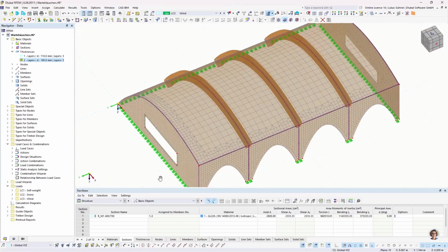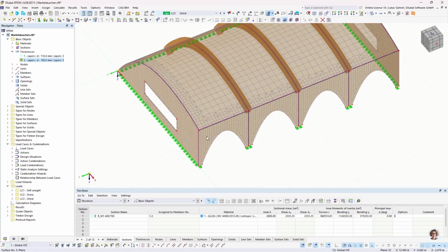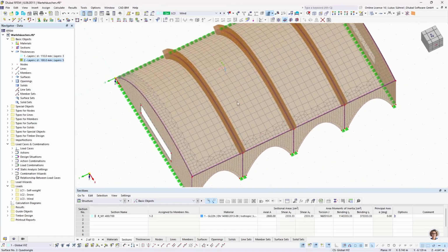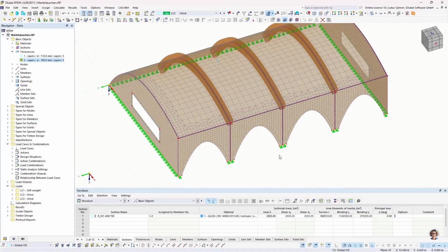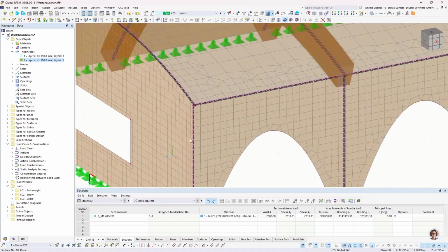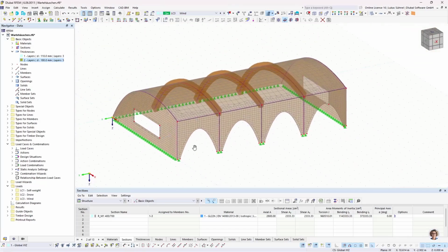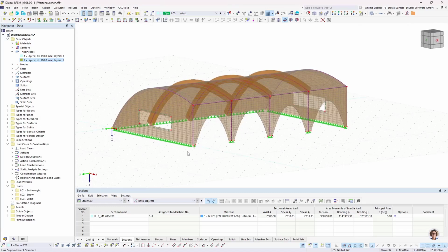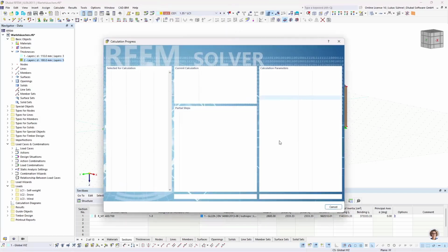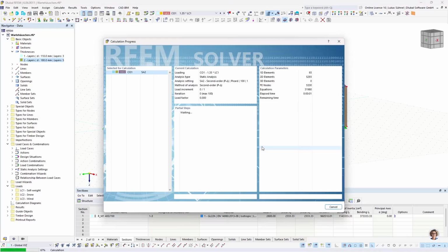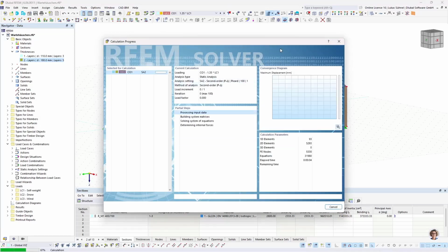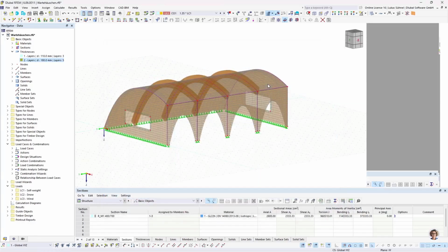But you can clearly see that the mesh refinement has been defined on these walls, except for the roof where I have the global FE mesh settings. And we can also see that I have these line hinges defined, and all the things that I showed here. And if everything is fine, we can also run a calculation and we can get the results. And this step, running the calculation, can also be triggered via the Grasshopper component. Yeah, so that's also possible.